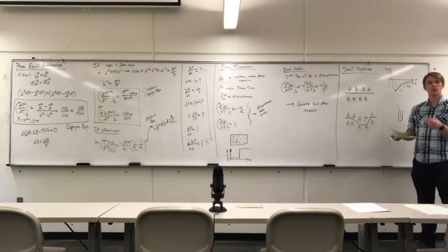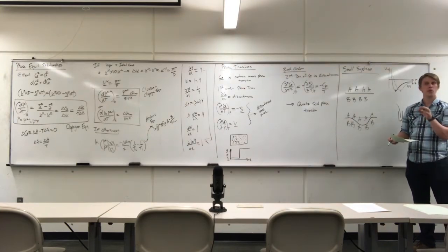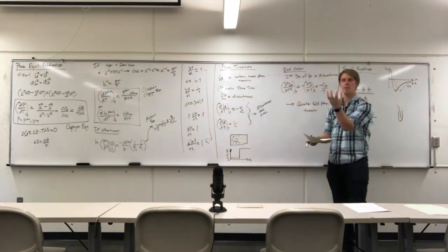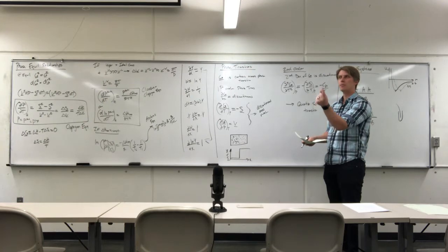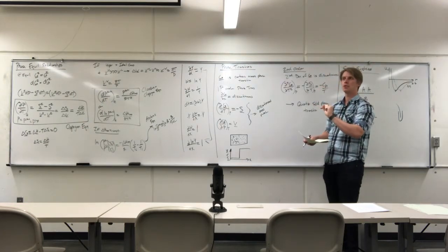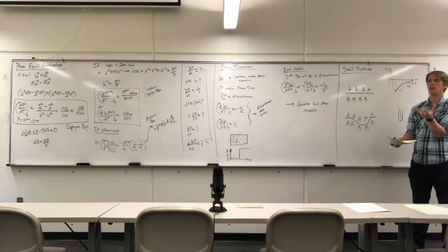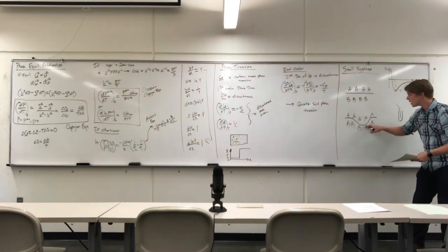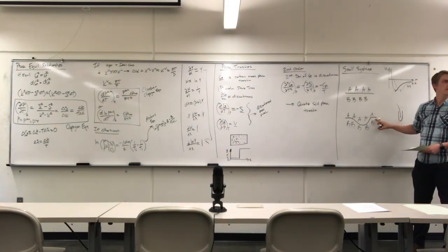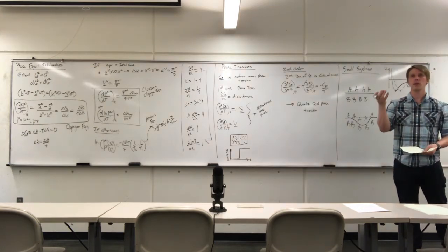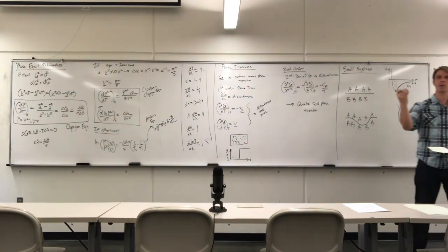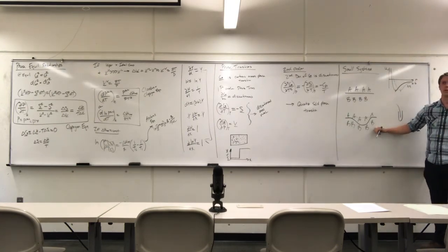Now, the reason why droplets are spherical is that a sphere is the shape that minimizes the surface area to volume ratio. There is no other shape in nature where you can have the same quantity of a material with the smallest interface. So that's why a droplet is the way that liquids like to behave, and bubbles too. They're always spherical in shape because that is the way that minimizes the contact between the two different phases. This is the case when you're boiling water: you can have an interface and a surface tension between liquid water and vapor water. You can have an interface and surface tension between an oil and a water-based phase. So there's always going to be surface tension between any two phases.